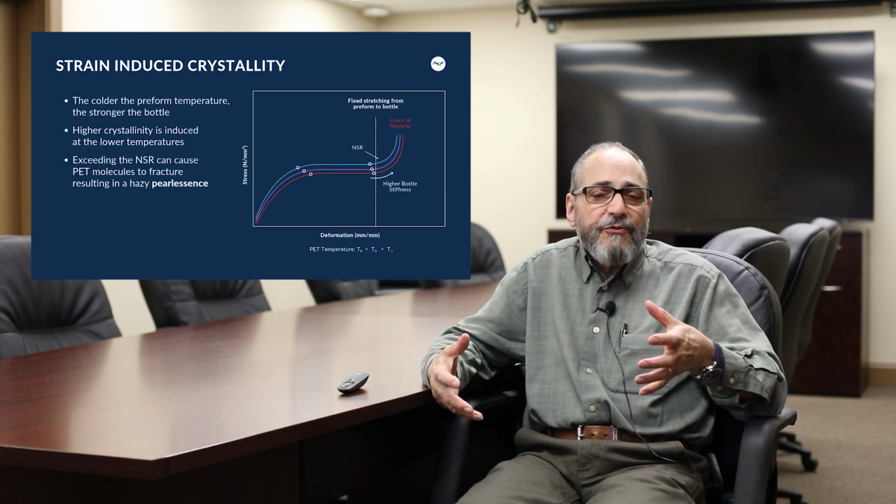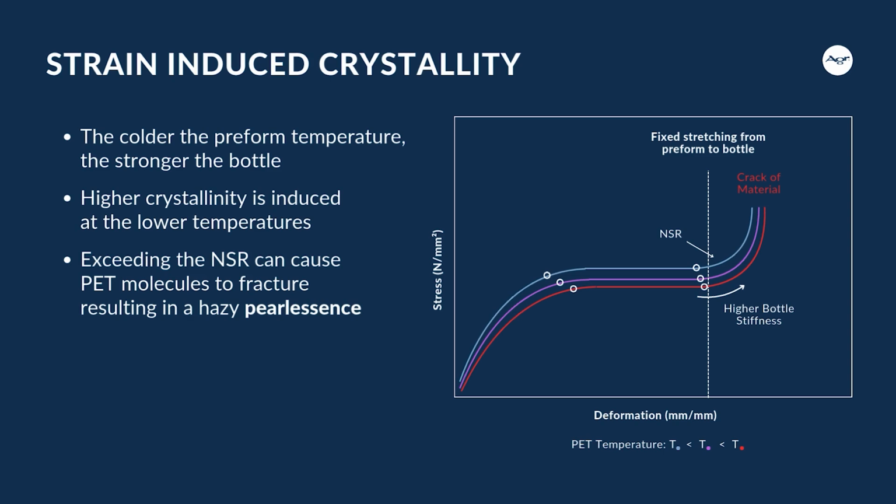Preform temperature has a big effect on that also. I mentioned the proper heat. You want to have your lamp set up so you get the maximum infrared penetration into the preform wall. If you're running at very low output percentages, either overall output or in individual lamps, below 70%, you're not going to get infrared energy penetrating the wall of the preform. You're just baking it with heat. And if you have your preform temperature too hot, you get the same result.